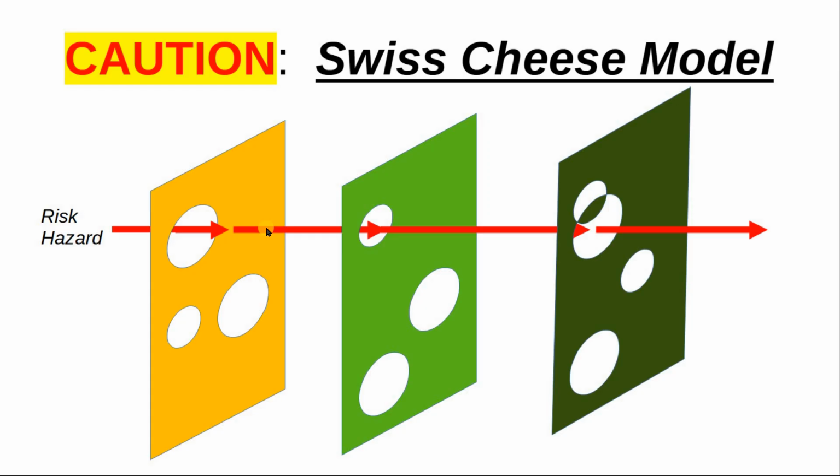I will give you an example for that. In most cases, the vendor does not care about the temperature of your pipes and tubes. Some companies say any pipes or tubes with temperature above 60 degrees C within 2 meters from the ground level should be insulated. Here what they're looking for is protecting the people walking by, the technician, whoever is there on the site.